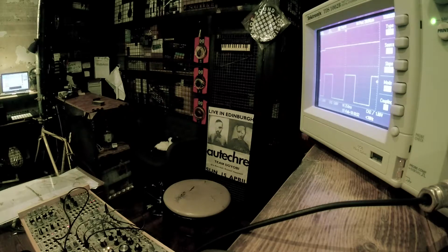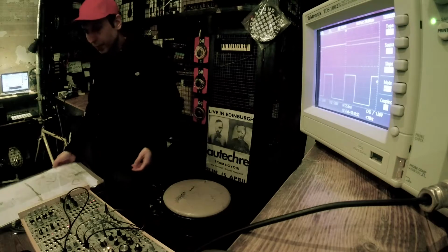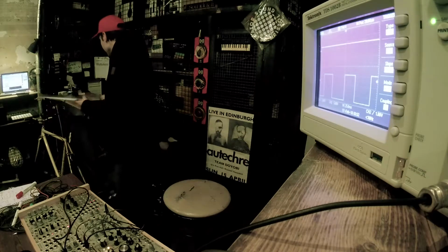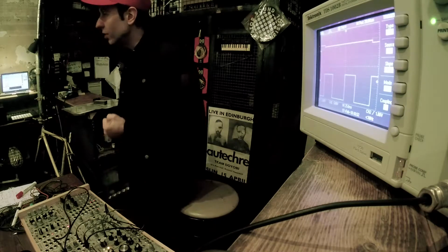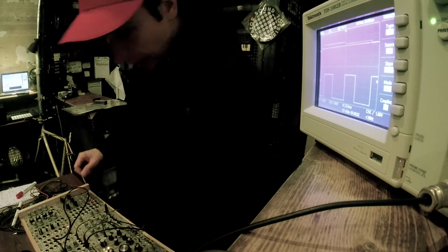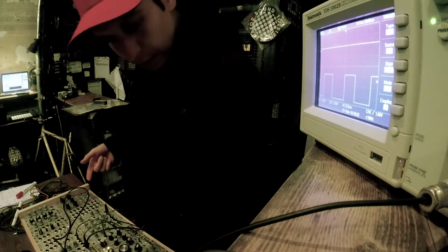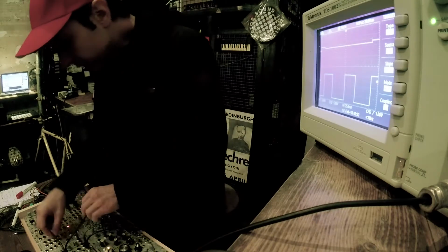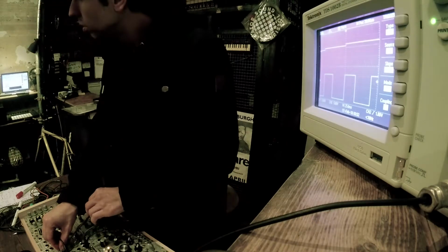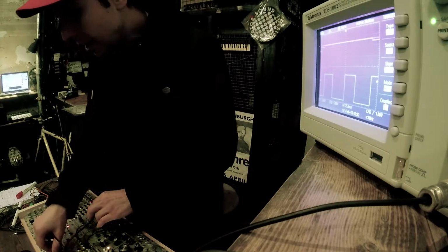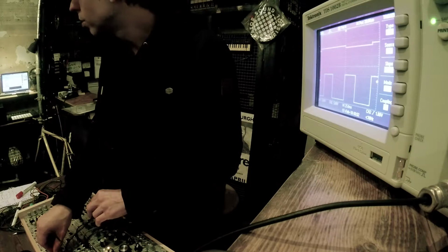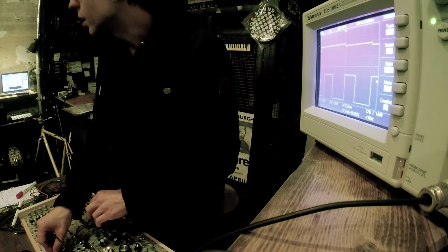Yeah, so that's the message: most of these inputs, without it being very explicit, do have an offset and a gain stage for the CV inputs. So if I look at this oscillator here, my frequency CV control changes the gain, and my actual frequency knob does the offset.